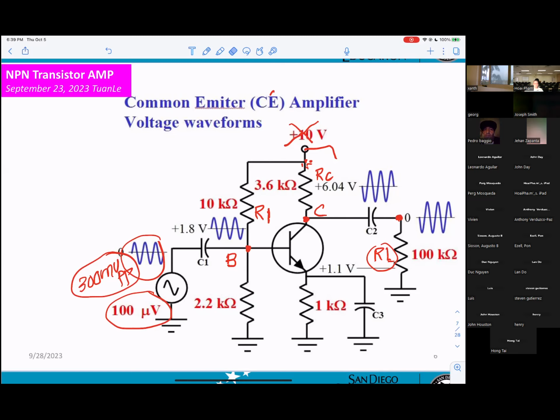Remember, I don't have a generator and a scope in here to show you, I'll show you the meter type on Friday. You have to emphasize that. That means if you want the small voltage, then from the normal output of the generator, you have to use the minus 20 dB button. Then you can go down to 300 millivolt.